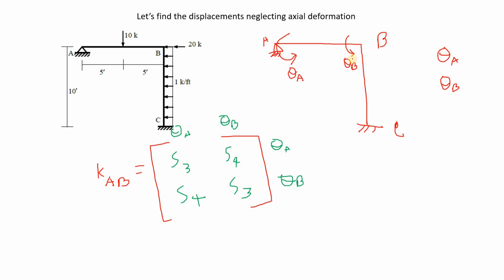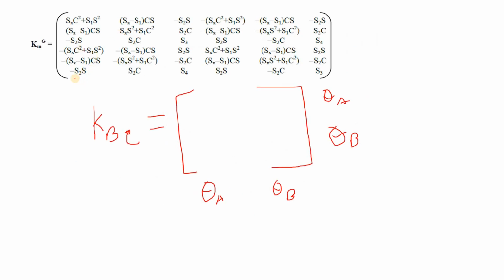So this displacement becomes the number 3 displacement. Because in this case, for member BC, these equations from here to here are the B variables, UB, VB, theta B, and these three are the C variables, UC, VC, and theta C. But we already know that these are 0 because there is a fixed support there.